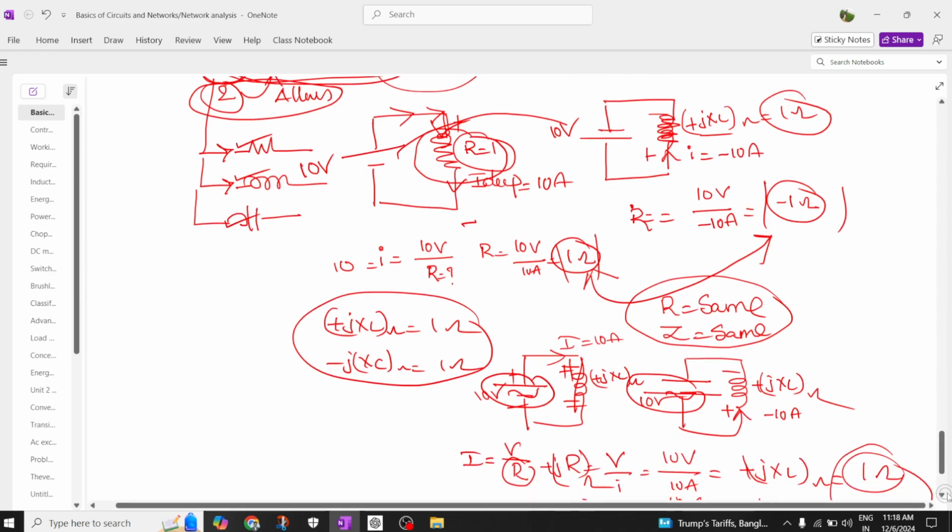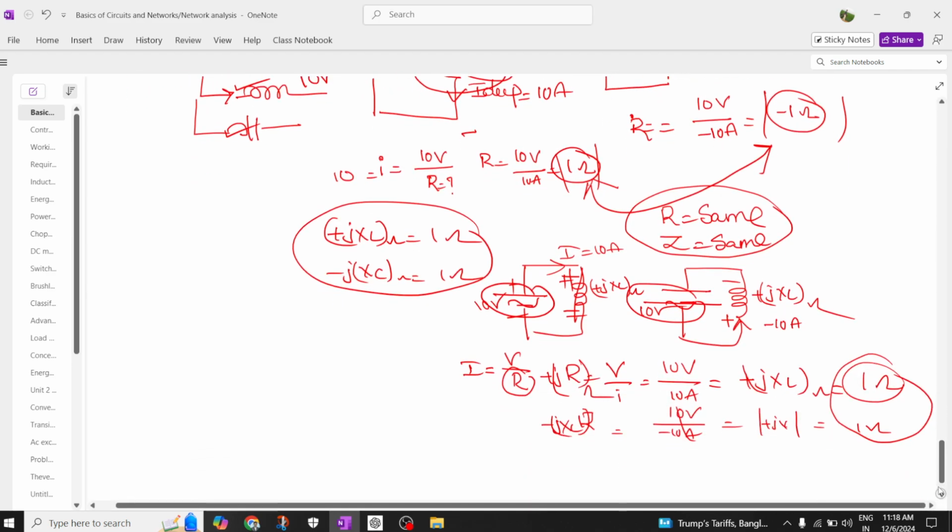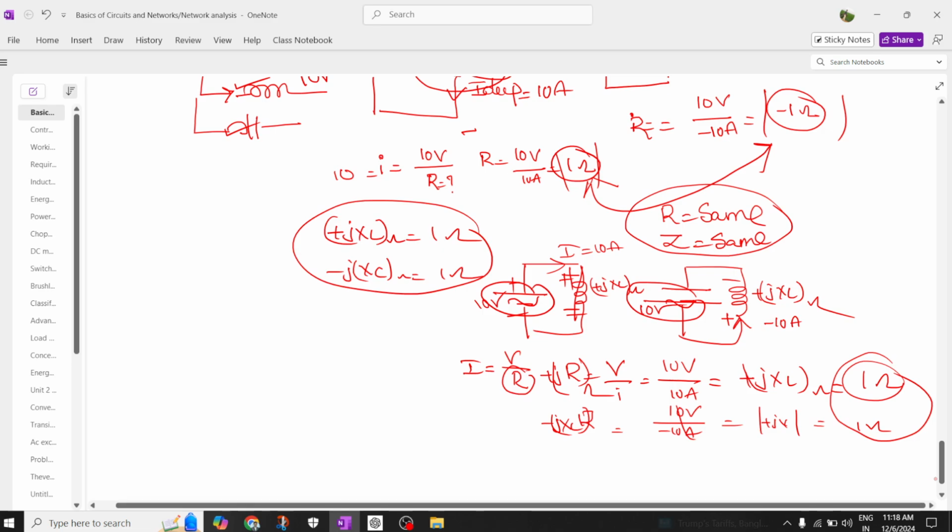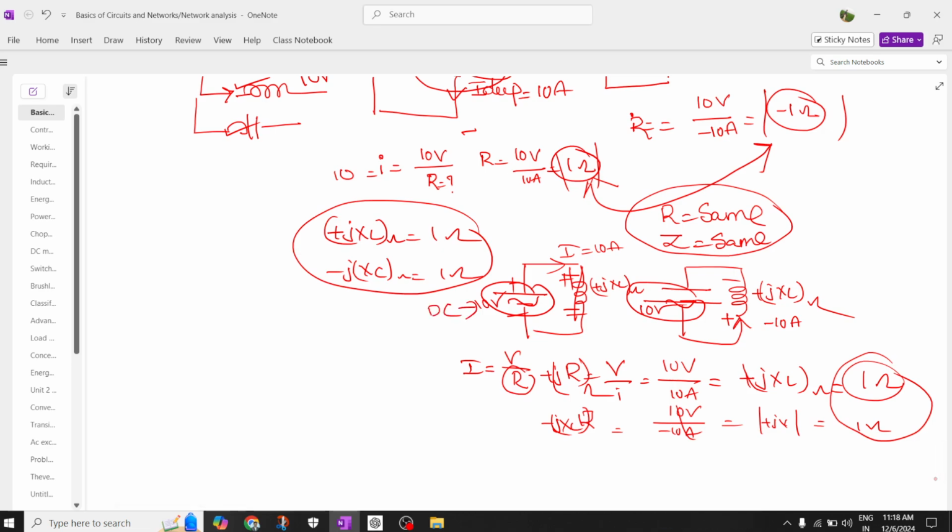Okay, so the beauty of why I converted this DC to AC is, DC we cannot directly write down as inductance. We need to transform it. But when you change the type of source to an AC source, the analysis becomes easier. The inductor can be represented in ohms, which is nothing but plus jXL. The capacitor can be represented in ohms as minus jXC. So easily you can transform and easily you can express in ohms. This plays a major role.